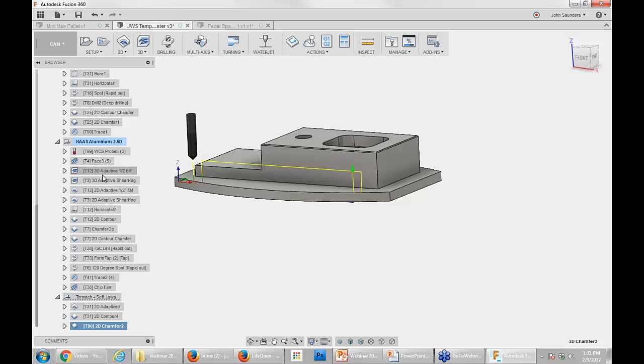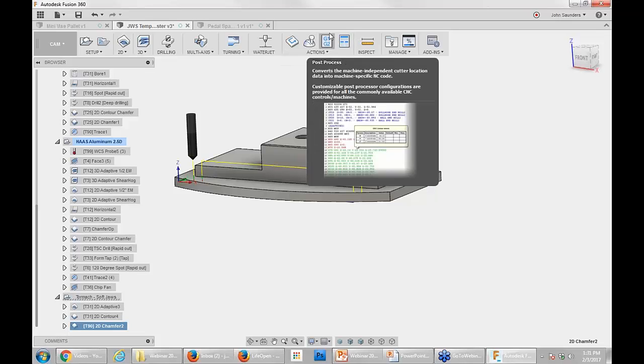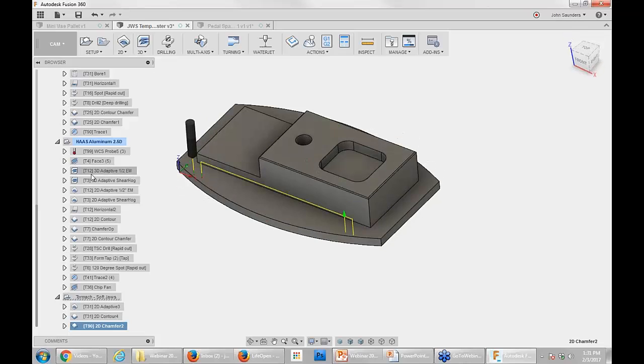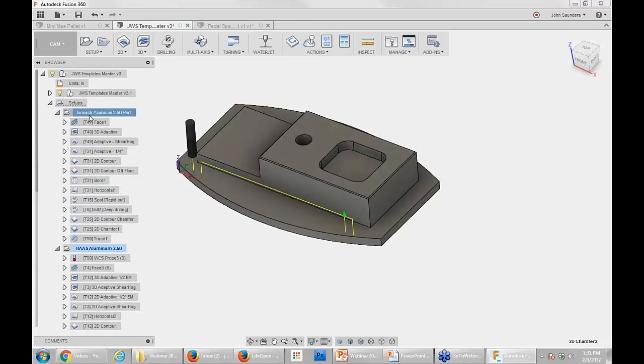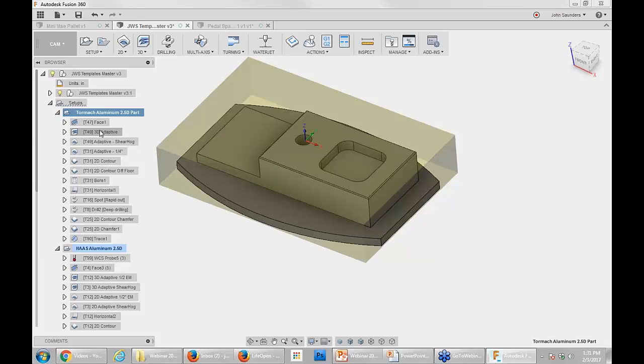It gives me the confidence, especially with the Haas, because I'm pushing tools harder, and I want to know, for instance, little things like tool 17 in my Haas is a 3/8 inch standard end mill. Tool 18 is the identical end mill, but is only used for finishing. So that end mill is going to stay sharper and cleaner longer, which is going to help me hold tighter tolerances on my part. So I highly recommend you guys do something like this with a template master.